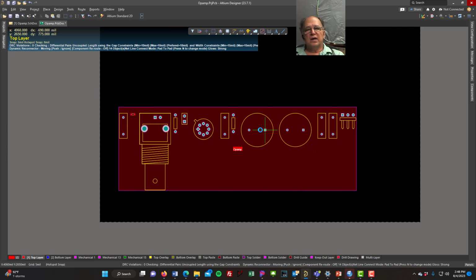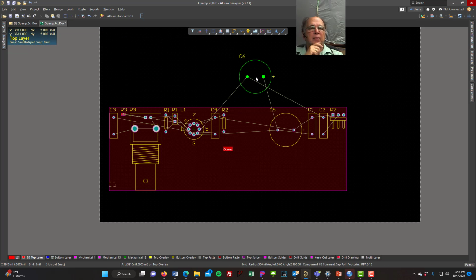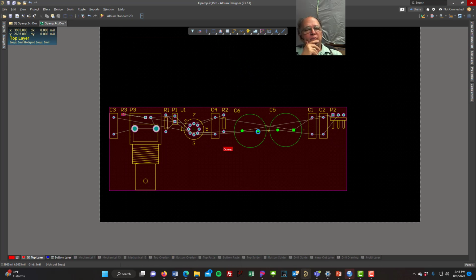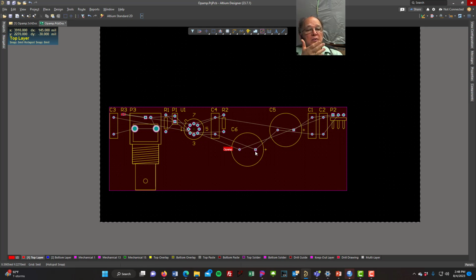And they're all inside this room. This magenta colored box is the room. So all my parts that were on that sheet went into one room, and here they are. Now if I take a part out of the room, see it turn green. Green is Altium's way of saying there's a problem. Turns green. Put the part back in the room. I got them too close there. And it's yellow. Right, if I did this, they overlap, they're green, they're too close.